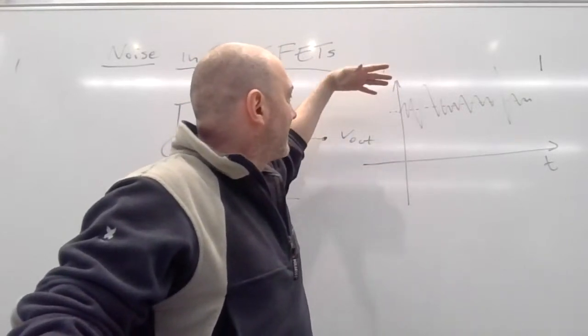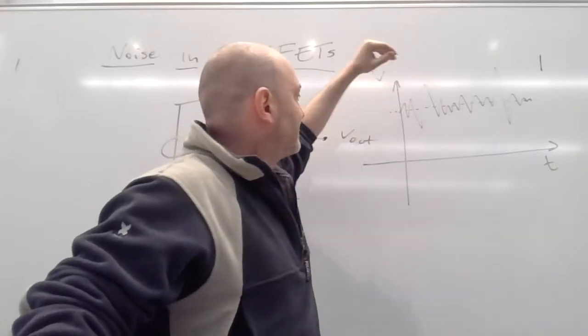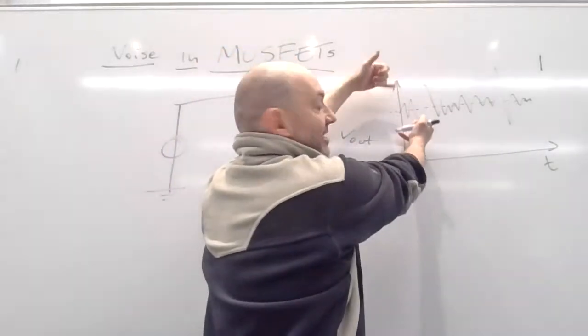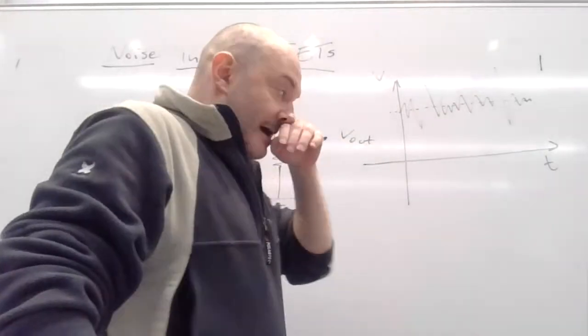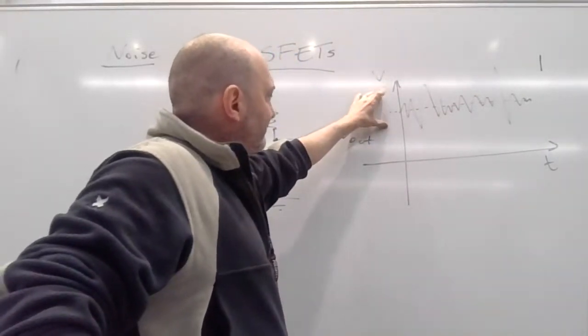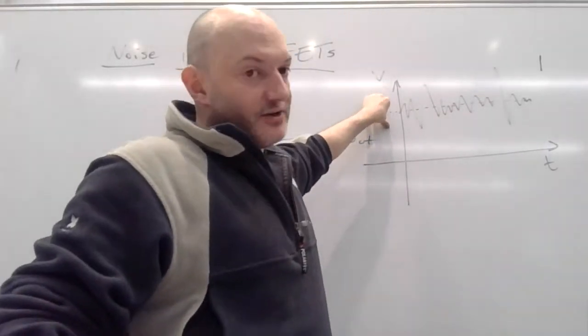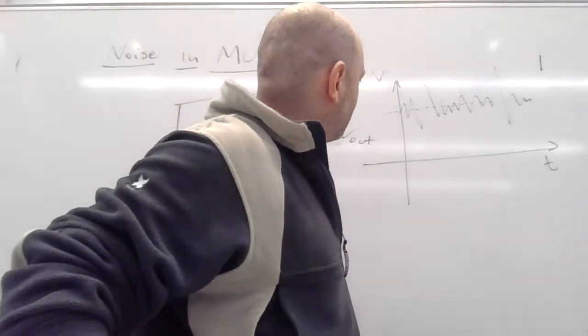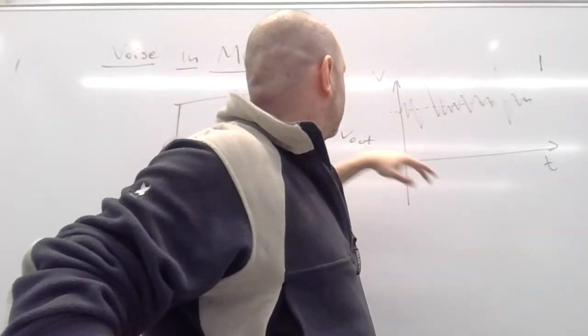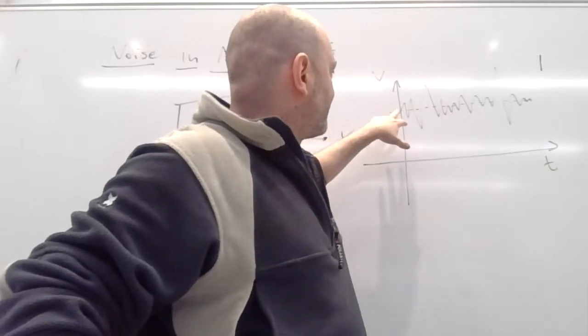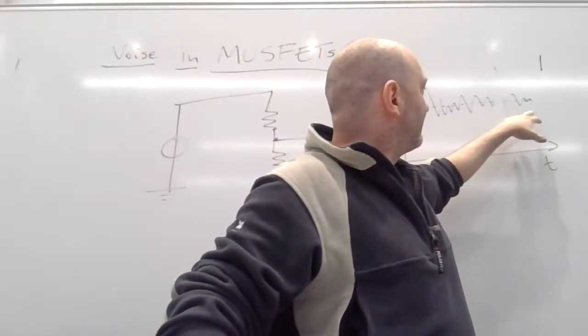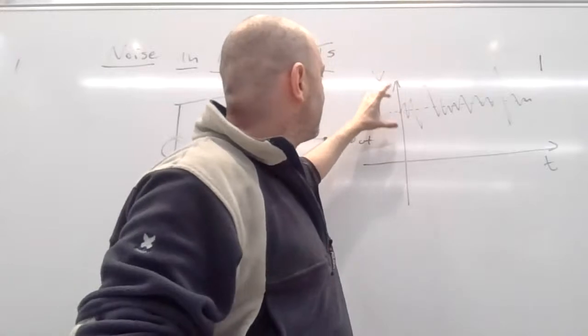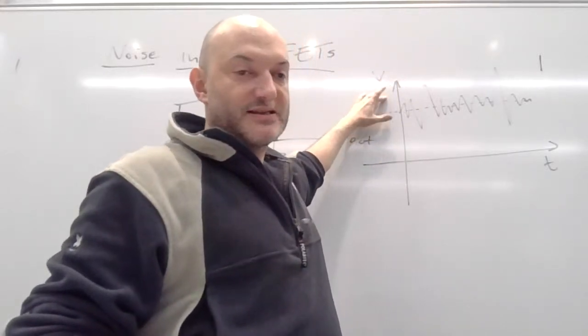But we need to have a way to quantify this fluctuation, both the behavior as a time series as well as the amplitude. Now, the amplitude is quantified very easily by the RMS value. So typically this is done by measuring the voltage as a function of time, and then seeing where the RMS value is across the average.